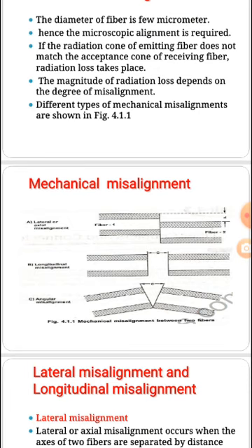There are two fibers we are connecting. The core to core interfacing is very much essential. Similarly, cladding to cladding interface. So this is a small mechanical misalignment. This causes heavy losses. A loss of optical power means loss of information. We can say that the information and light power, both we can interrelate.